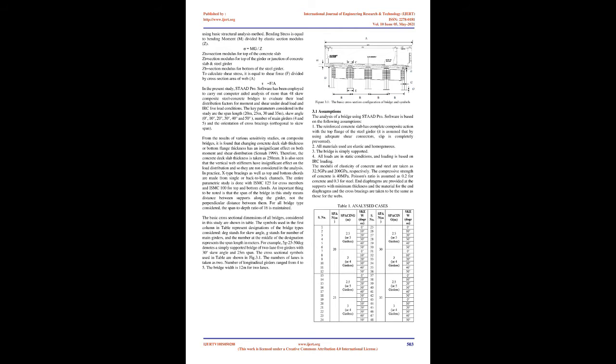The parameters investigated in this analytical study were the span length, slab width, and skew angle. The finite element analysis, FEA, results for skewed bridges were compared to the reference straight bridges as well as the American Association for State Highway and Transportation Officials, AASHTO, standard specifications and LRFD procedures. A total of 96 case study bridges were analyzed and subjected to AASHTO HS20 design trucks positioned close to one edge on each bridge to produce maximum bending in the slab.